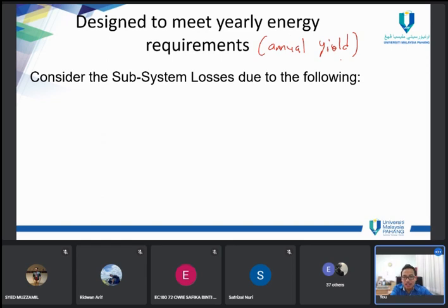What are those things? First of all, the things that we have to consider after this is the inverter efficiency. The difference in the efficiency of the inverter will totally reflect to the output of our PV system. That efficiency is critical when you are going to install a mega scale or large scale solar system size, so it really affects that. Choosing the inverter with the highest efficiency is the most desirable one.